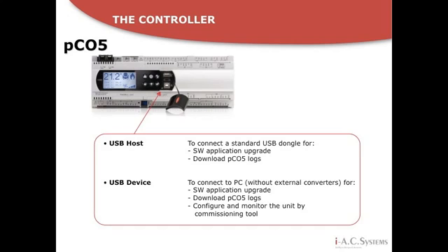This port is useful for a software update or log downloads, as well as for commissioning purposes. Thanks to the Pico Manager software, downloadable free of charge from the Carel KSA website, it is extremely easy to commission and configure an air handling unit or record live data from the controller, such as temperatures, device conditions, alarms, etc., during a running operation of the unit.